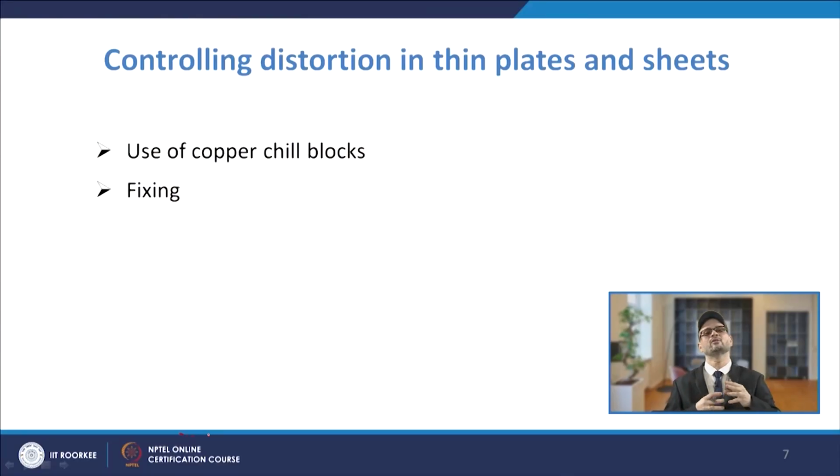Then we also use water cooled jigs many a time. You have copper tubes bridged to the copper holding clamps, and water is circulated through those tubes during the welding. That decreases the temperature, and it is likely that your distortion will be smaller.